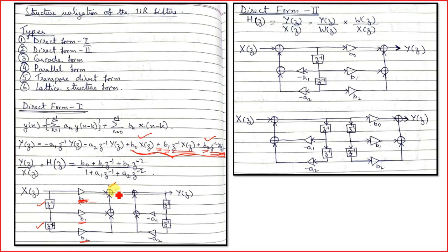So over here, see, this input region we have implemented. Now if you have further input components which are getting added up, then below this b2 you'll have to add those components to complete this input and its delays getting multiplied with the filter coefficients, and then you can get this region.